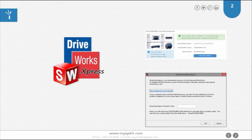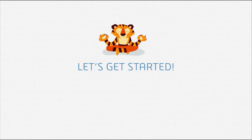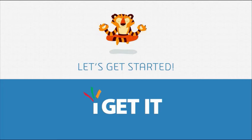So to start, if you have never used an Express tool in SOLIDWORKS, they require activation. Now, DriveWorksXpress does come free with every seat of SOLIDWORKS, but you still need to go to mysolidworks.com/express, and if you don't already have a profile for mysolidworks.com, you can set it up and enter your product key there, and once you get to that point, they'll give you an activation code, and then when you go to actually launch DriveWorksXpress, it'll just prompt you to enter that code, and you just have to do that once. So every time you go back in the future, you don't have to worry about having to do that code each time.